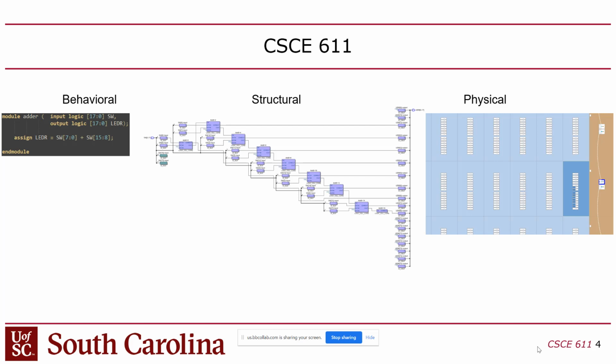Yes? Is there any algorithm which can optimize this process of placing things and wiring them? Well, it depends what you mean by optimize. The algorithm that they use is simulated annealing, which is essentially just random selection. They just randomly allocate it, and if that random allocation is better than the previous attempt, they keep it. Otherwise, they throw it away and try again. That's basically the process they use. It's a little bit more complicated than that, but you can't do it optimally.